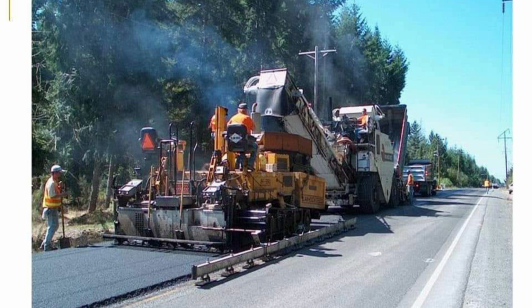Especially the Marshall stability test is used to select a proper blend, and also an asphalt content that can bear the maximum load, having standard air voids with minimum flow. It is a huge process of asphalt selection, or the Marshall stability test.